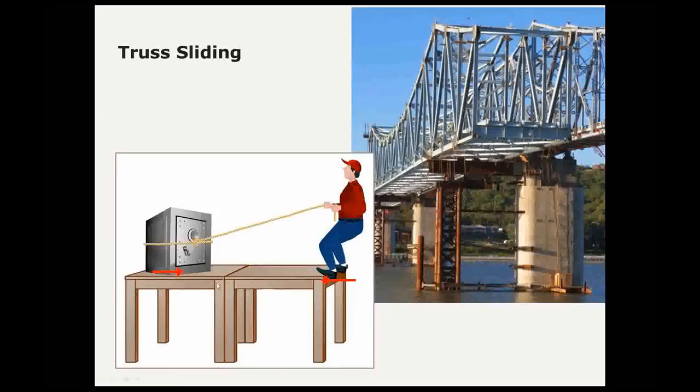As long as those two tables are in contact, those two forces oppose each other without imparting any net force on the table legs. So what you end up with is a net compression across the tabletops. So when we slid the bridge over, what we had was a net compressive force across the sliding girder and the cap of the permanent pier. So we didn't have any net force effects we had to consider on the design of the caisson strengthening or the stem reinforcement.